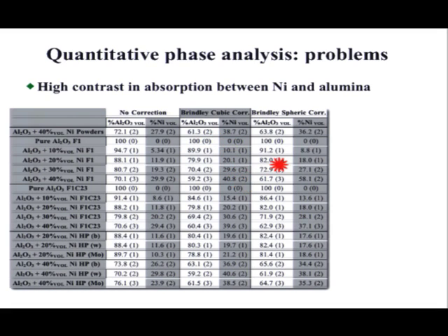And then, because we know the particle size from the SEM image, okay? If you don't know that, you get a little bit worse, okay? But then if you apply the spherical one, from the SEM image it's not clear if you have a spherical or cubic particle. Actually, it's not so good. So the Brindley correction, it may work, but only if you guess what you really have inside.